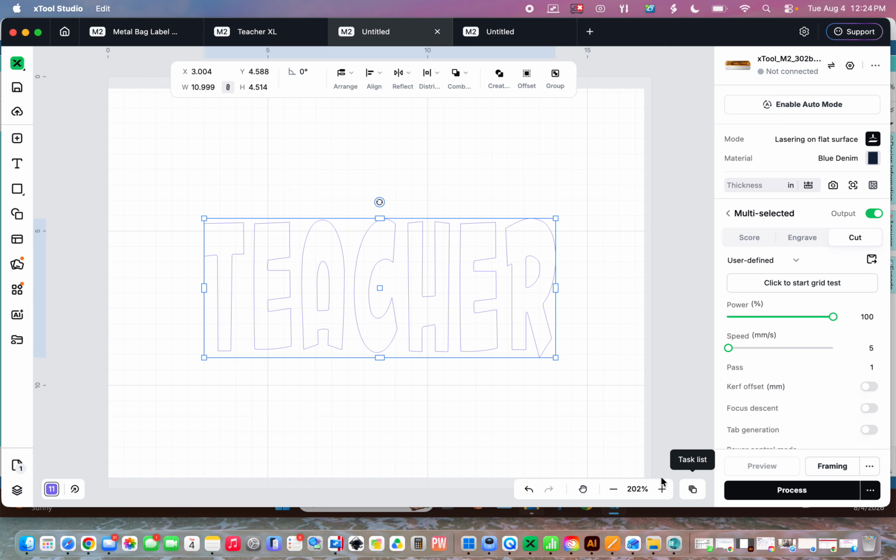If you're using a cutter machine, I would suggest having a very sticky mat. If it's new, that would be great, or if it's barely used, as long as it's very sticky. And I would say to either tape down the 4 corners or tape it all the way around the design to make sure it doesn't shift, especially if the mat isn't that sticky. That's why I suggest make sure your mat is very sticky, but if for some reason it's not, make sure you have it taped down extremely well so it will not shift while it's cutting.